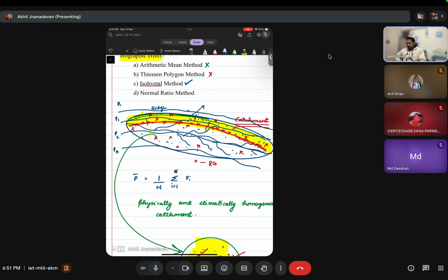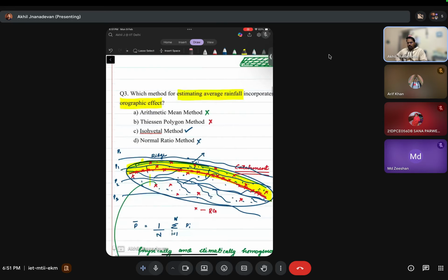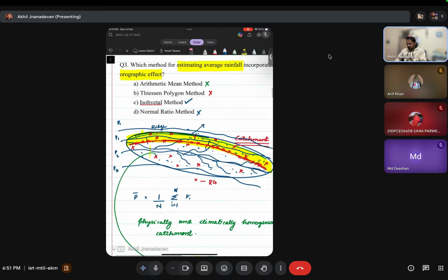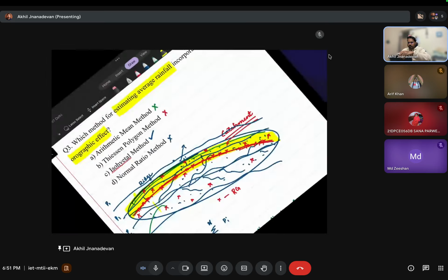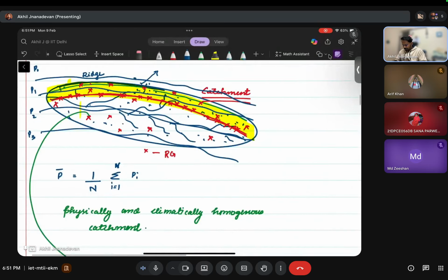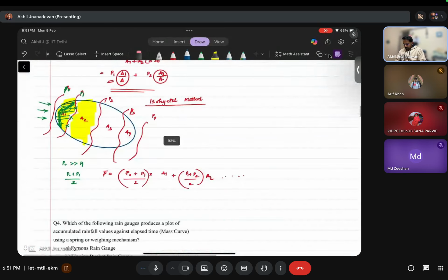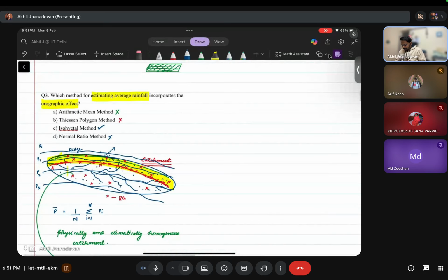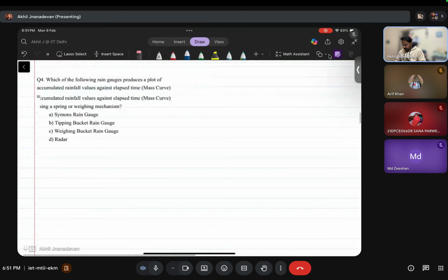This is not something that comes under estimating the average rainfall. If you remember correctly, this is something we use to find the missing rainfall. If we have a station and some rainfall readings are not there, we deal with this inconsistency with the help of methods like the normal ratio method and the arithmetic average method. So it is not a part of the average rainfall methods.